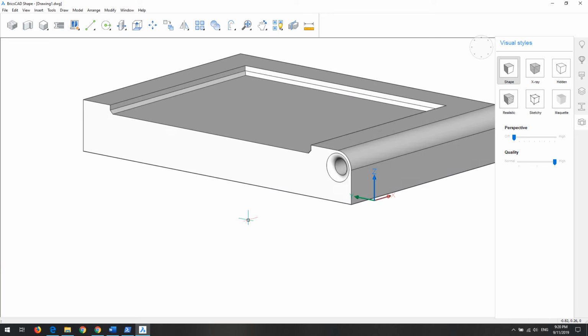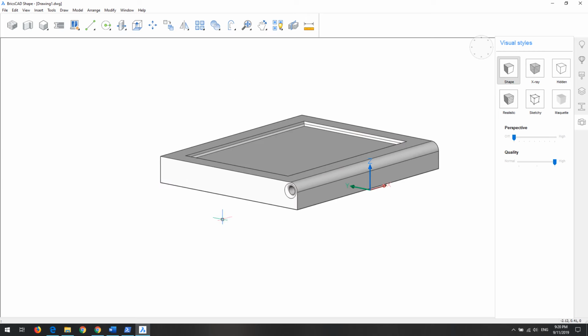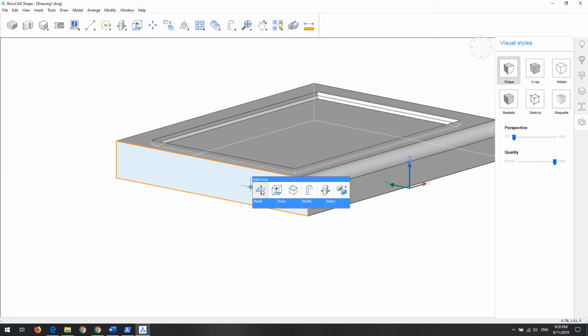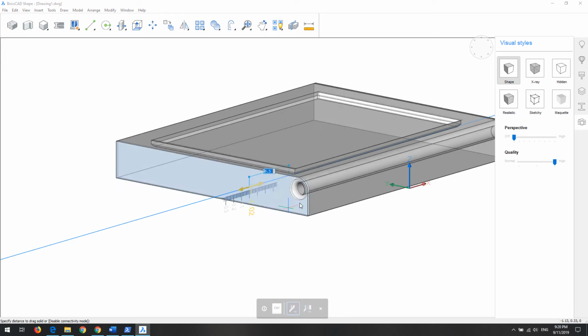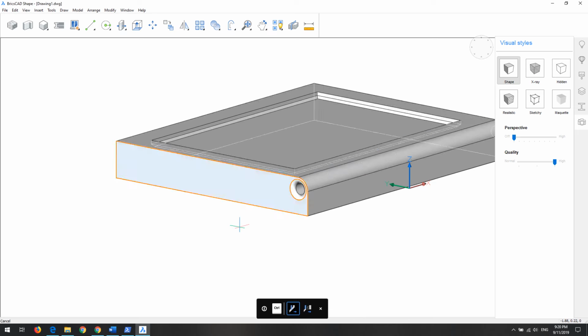So what happened with push and pull: you see it's not just moving the other side, it's removing the other side. See, this particular feature didn't maintain the other side shape. It's like cutting, also maintaining some feature, also a boolean cut. Let's undo. If we use some other tool, say a face move tool, you have push and pull, extrude definitely, but we can't use drag. Drag is dragging the whole body.